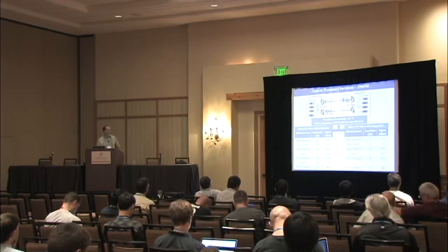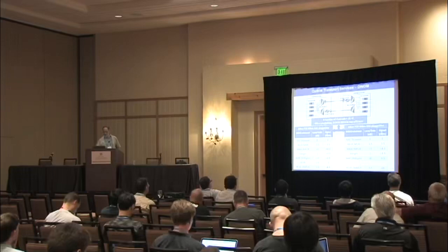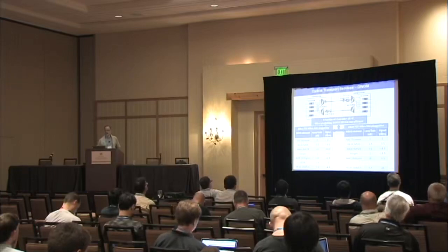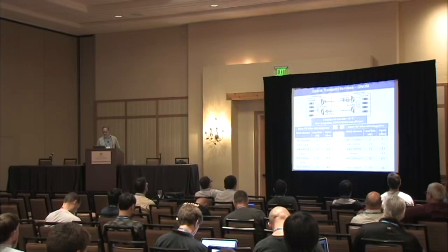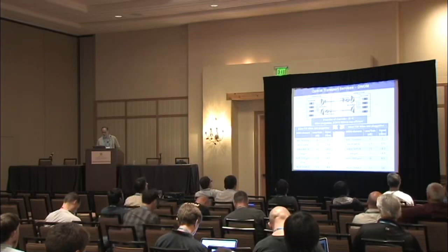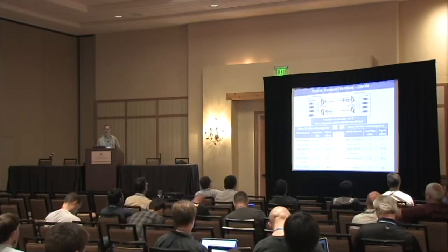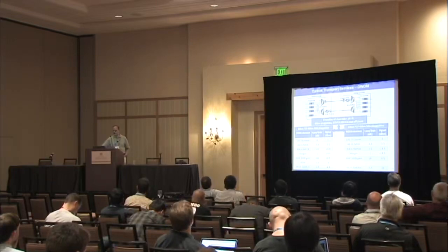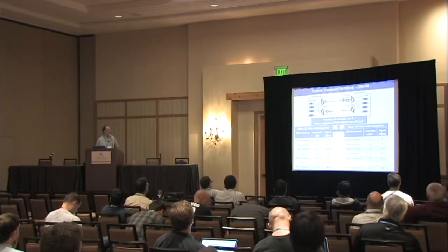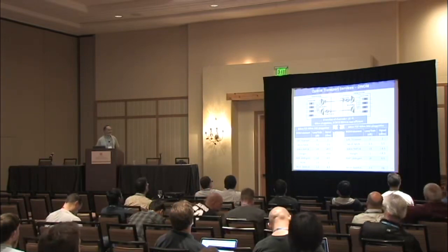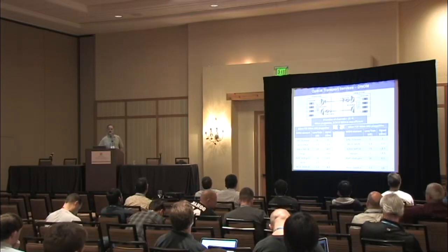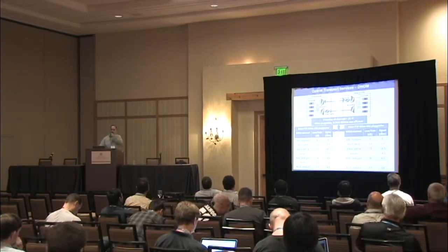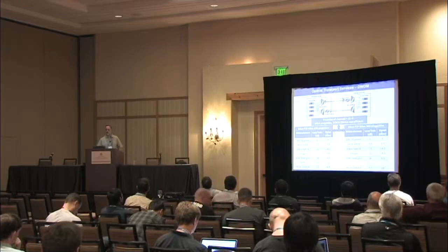Now, looking at the 80 kilometer optics, it's exactly the same calculation. I can use a lower grade amplifier of just 10 dB because I have more sensitivity. I don't need a DCM because I have enough dispersion tolerance. Again, doing the economical calculation, an empirical number is somewhere around 16 channels and beyond. I'm better off economically using 40 kilometer optics and an EDFA and dispersion compensation.